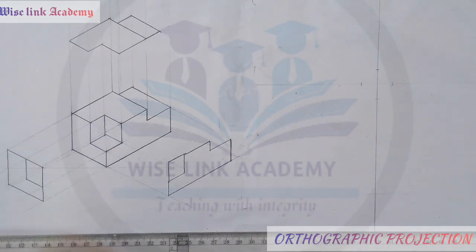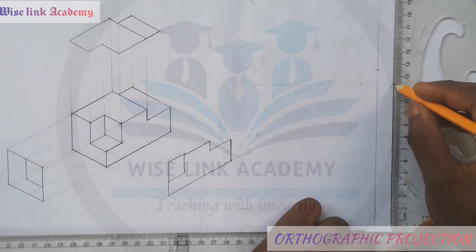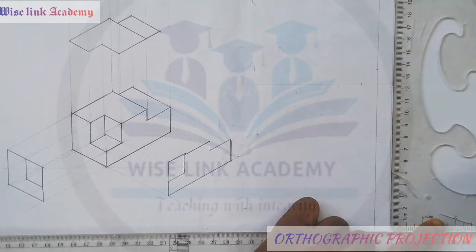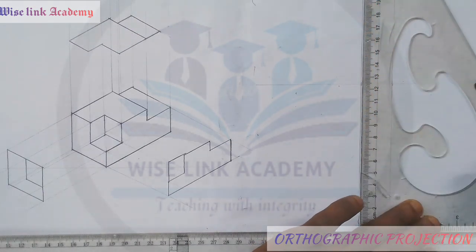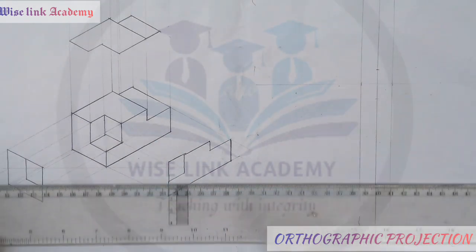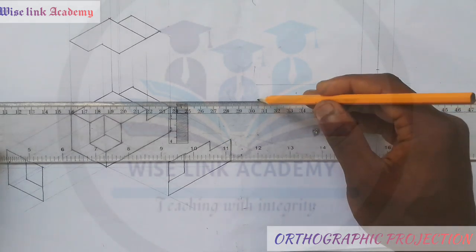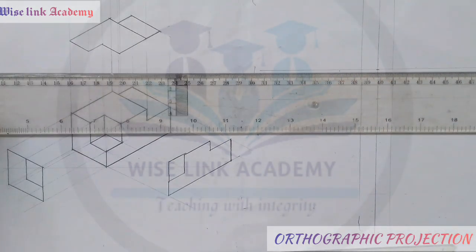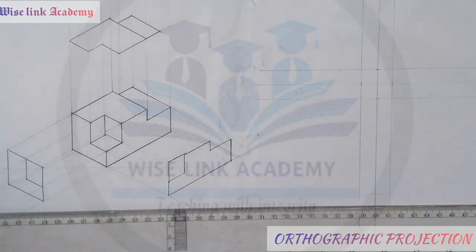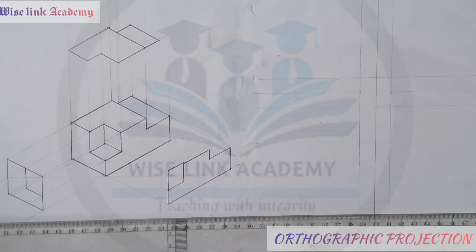With that, I will take my set square. I'll draw a vertical line this way at this point here, and also at this point here, a vertical line downwards. With my T-square, I'll draw the horizontal line this way. This is what I refer to as the orthographic axis, right? So now what do we do? How do we establish it?